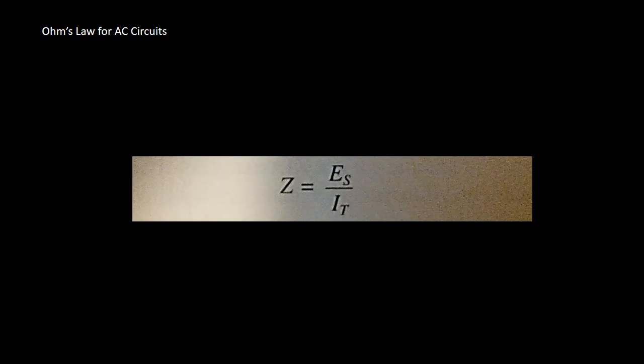RL circuit. In a circuit containing a resistance and an inductance in parallel, the voltage of each circuit element is the same as the source voltage. Further, there is no phase difference among the elements because they are all in parallel. There will, however, be a phase difference among the total and branch currents. The current is in phase with voltage in the resistive branch.